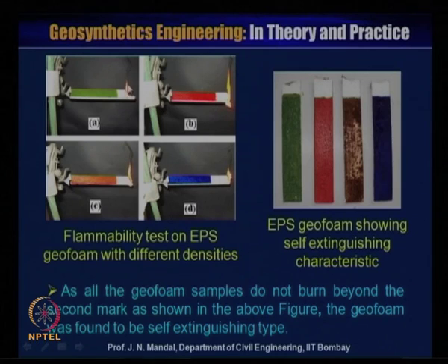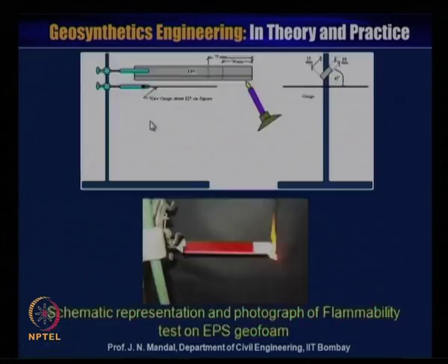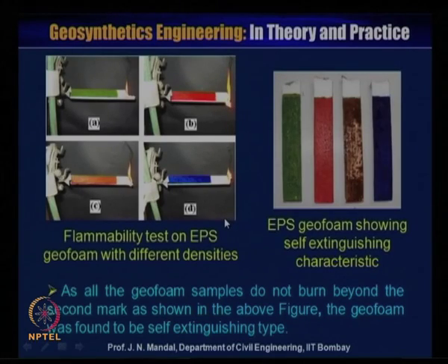In all cases you can see whatever is burning is not going behind this line. If it does not go behind this line, then that geofoam is found to be self-extinguishing type. So, here the EPS geofoam shows self-extinguishing characteristic.